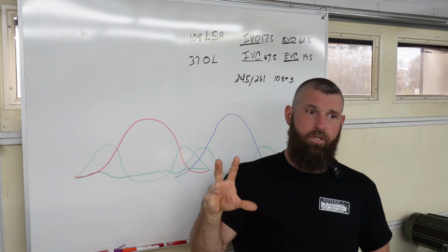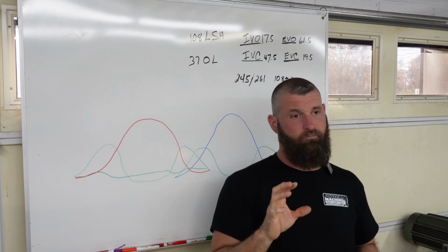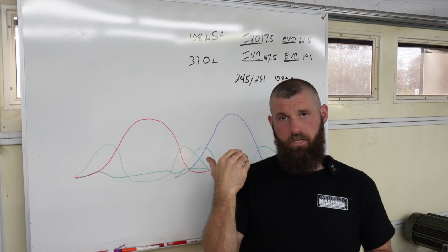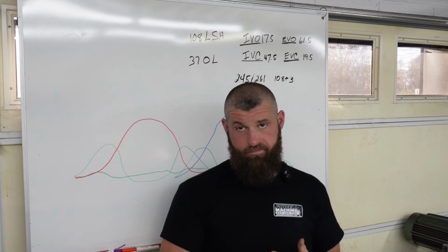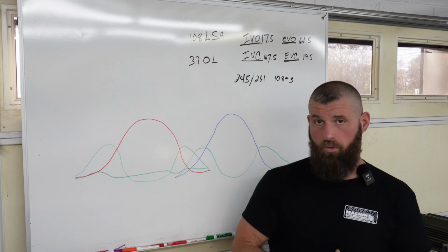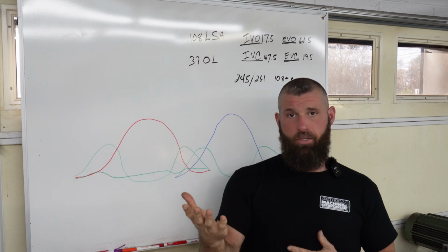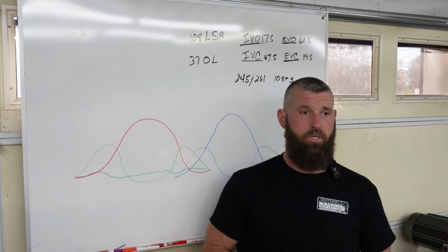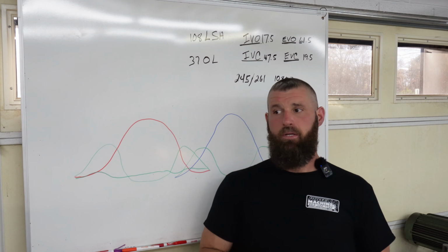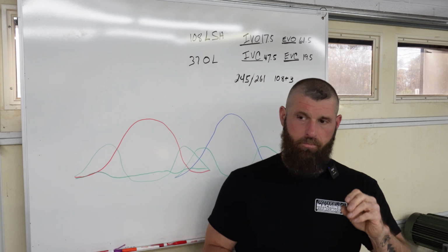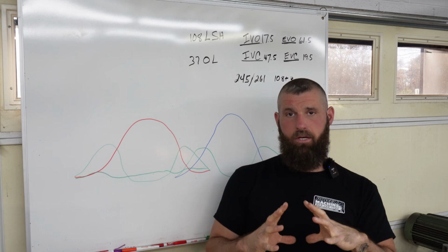Getting back to Bob's deal, because he's a 427, to make that work we have to have a 1-inch base circle with a 400 lobe. When you get down to 1-inch base circles, 900 base circles, all of that's fine, it's not a problem. But what is a problem, we've talked about this before, is you become acceleration limited because of the base circle.